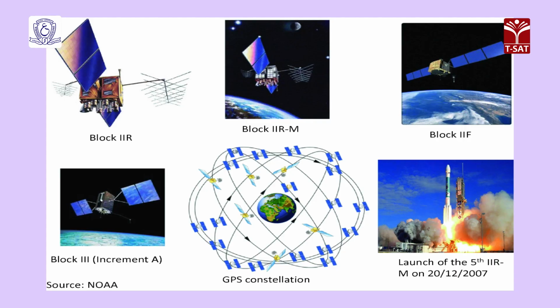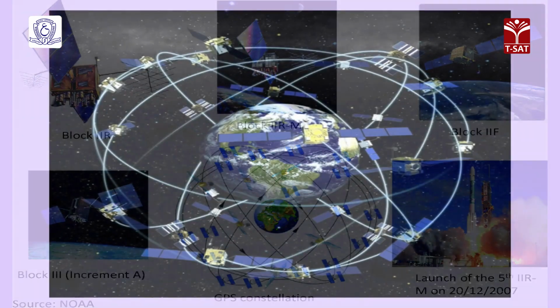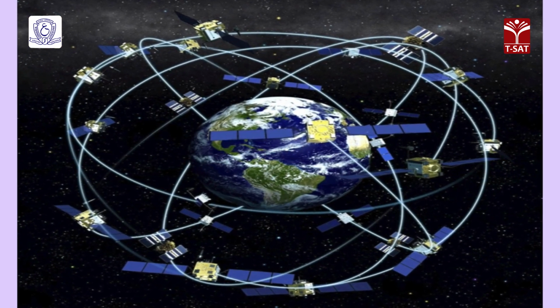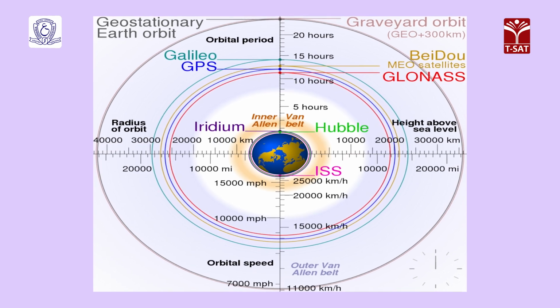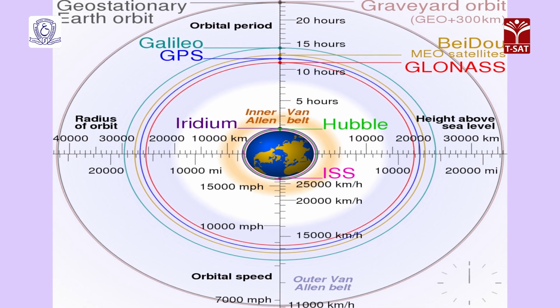The space segment consists of the complete constellation of orbiting GPS satellites. There were 11 Block 1 prototype satellites launched, 10 successful, followed by 24 Block 2 production units. Currently, only one Block 1 satellite is still operational, while 4 Block 2 backups remain in ground storage. The base size of the constellation includes 21 operational satellites with 3 orbiting backups, for a total of 24. They are located in 6 orbits at approximately 20,200 km altitude.